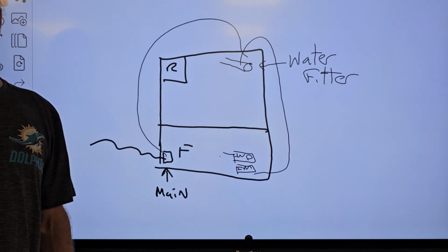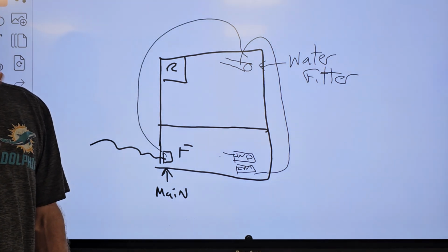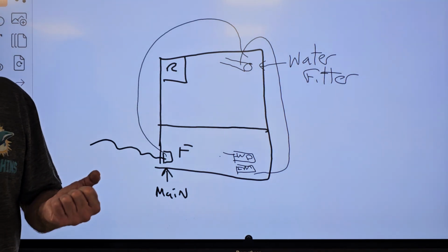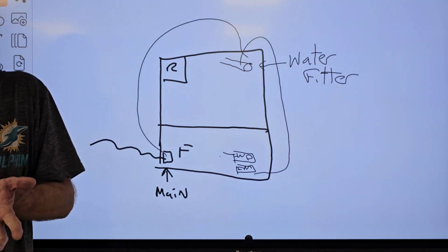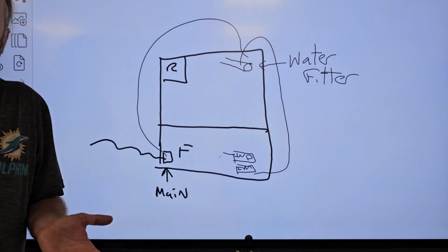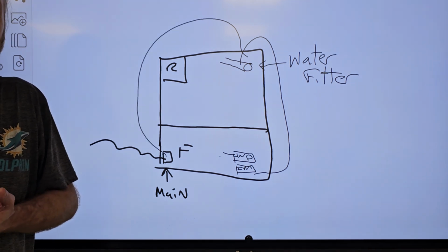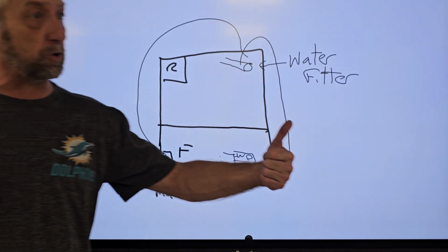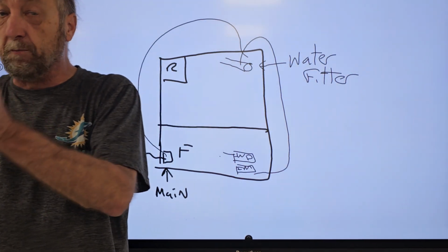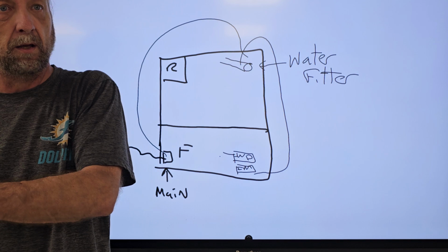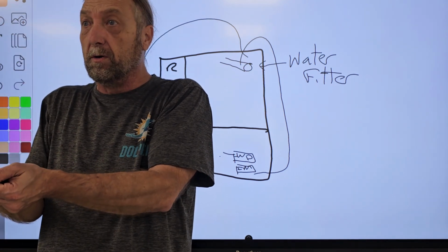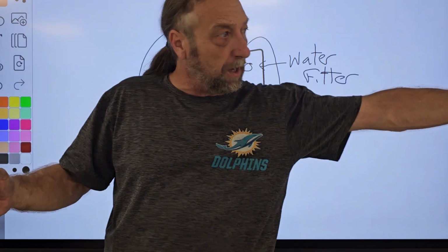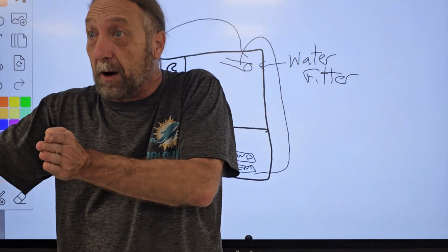We're going to look at this refrigerator so you guys can see it, but I want to go over it first, because your understanding of all this stuff is important. Even something as simple as the water flowing through the machine, because guys call me and say, I got no water here. Well, you have to backtrack. Where do you have water? Just like an electrical troubleshooting problem. If my motor's not working, I want to know if I have power to the motor. If I have power and it works, that's my problem. But if I don't have power, I have to find out what in that circuit is stopping power getting there.